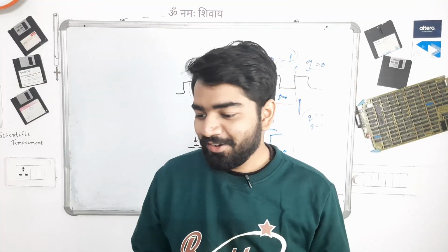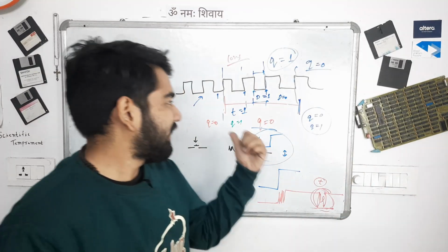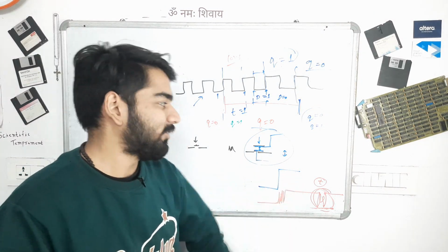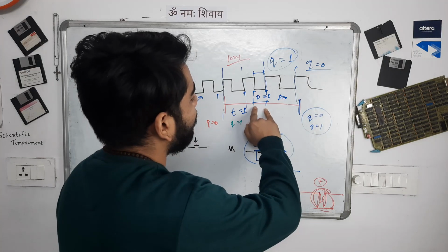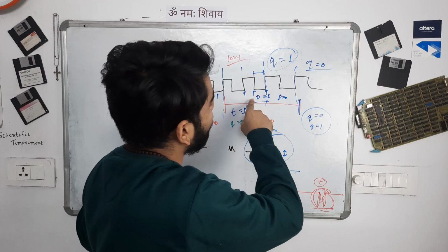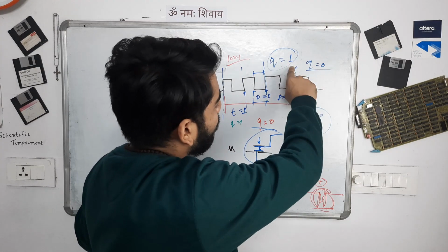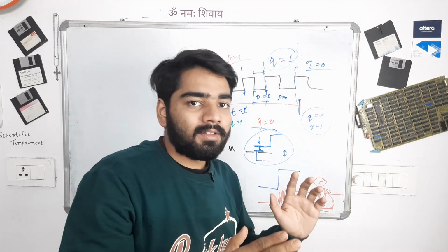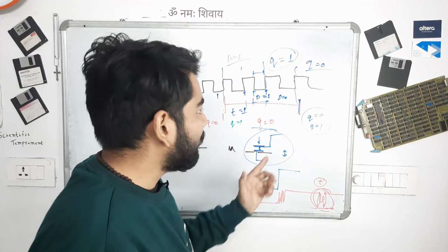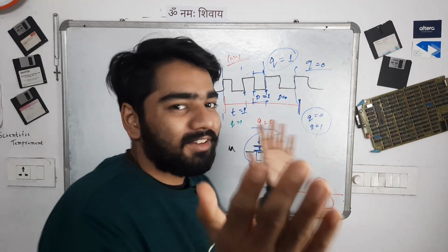Alright, so we have implemented all the flip-flops on the FPGA and we saw the anomaly which was caused due to very high clock speeds, and button bouncing effect, okay? Here I couldn't show you the delay between the signals and the output, because when I set D is equal to 1 here, there will be some amount of delay before Q will become 1, because the rising edge needs to be encountered before D is transferred to Q, right? Here I couldn't show that because the clock was so fast that the rising edge came very fast, right?